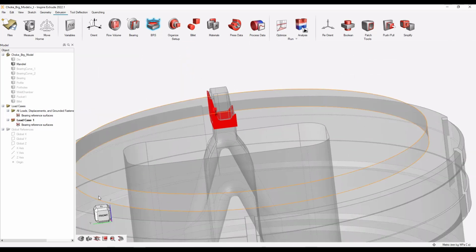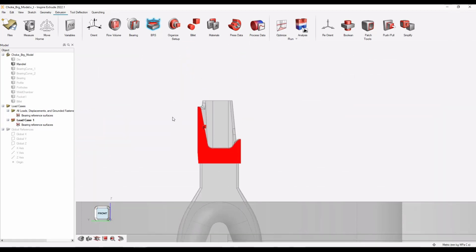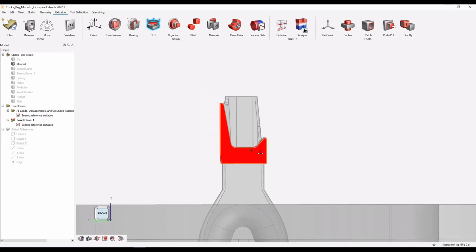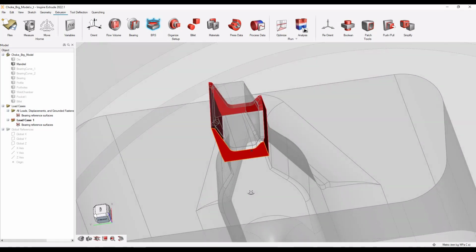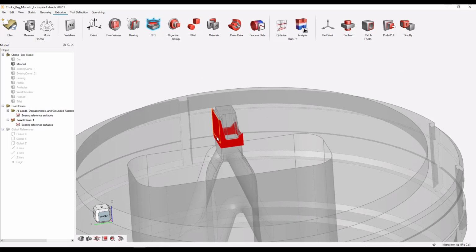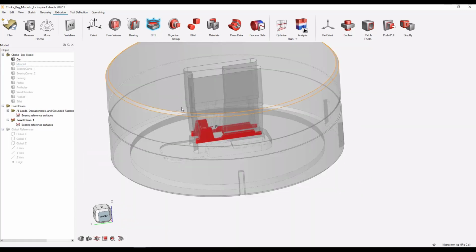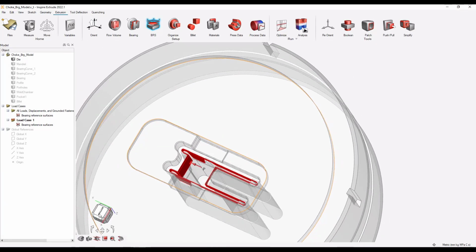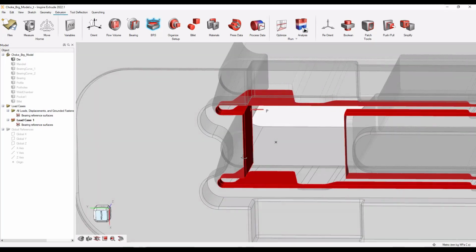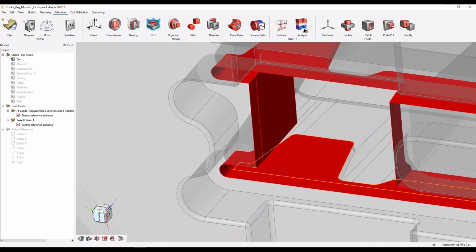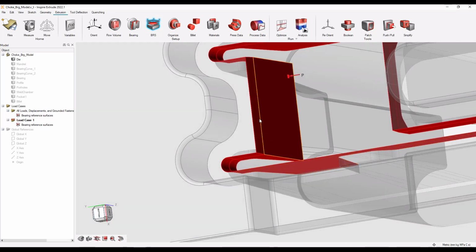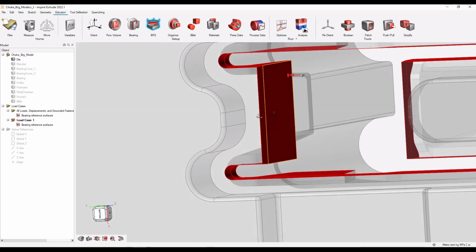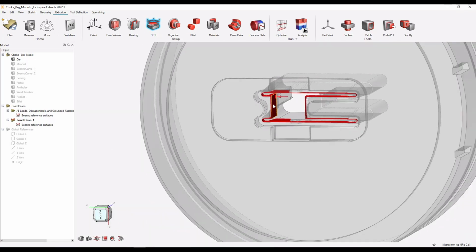properly. So what we can do is deselect everything first, and select only these portions. So this will be my bearing reference surface for the mandrel. I will do the same for the die as well. Just check it for the die. Yes, for the die it has detected properly. Here you can see this is the reference surface, this is your choke bearings, and this is the straight cross section of your profile. This way you can quickly check it.